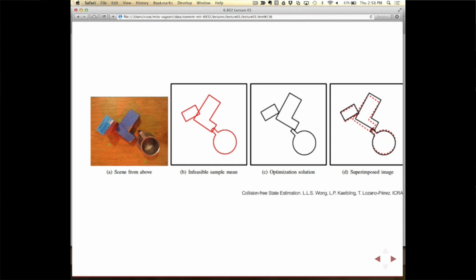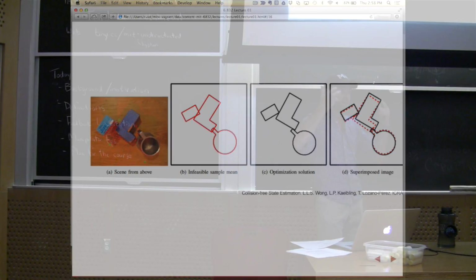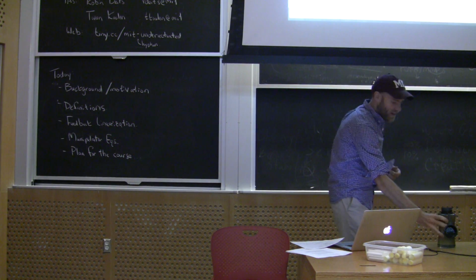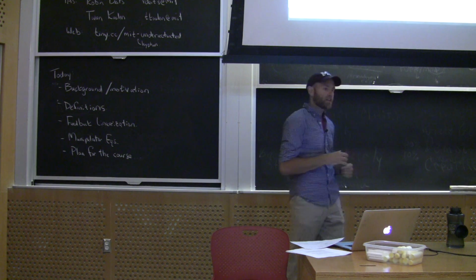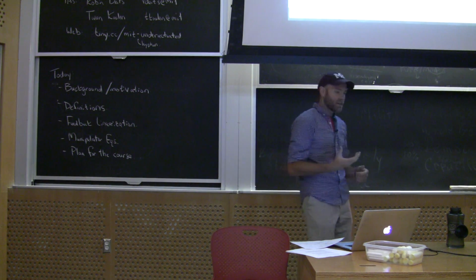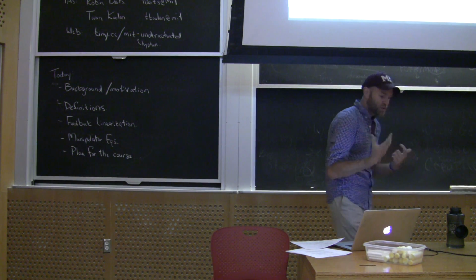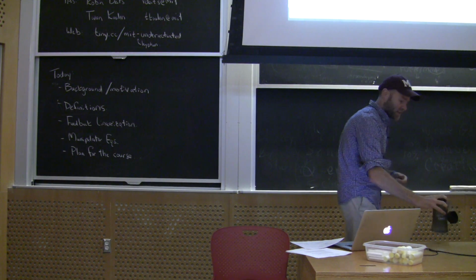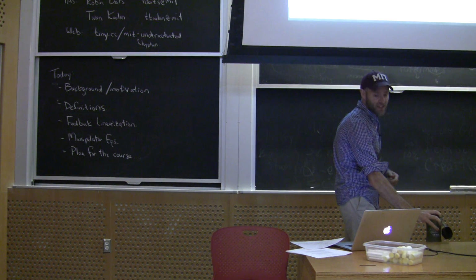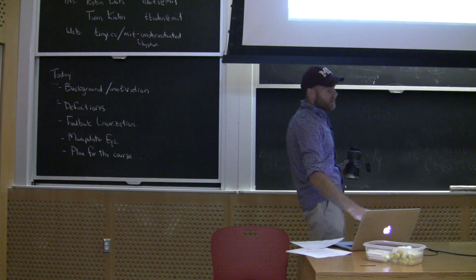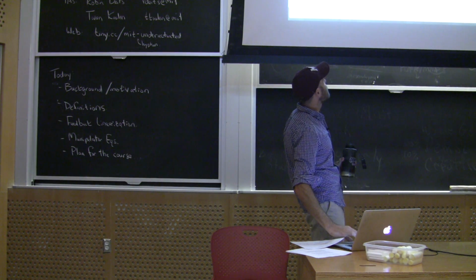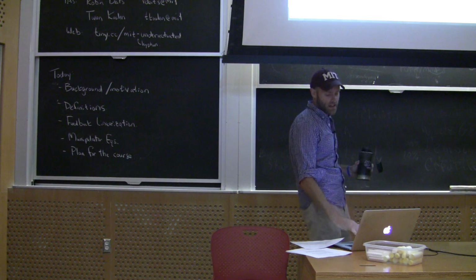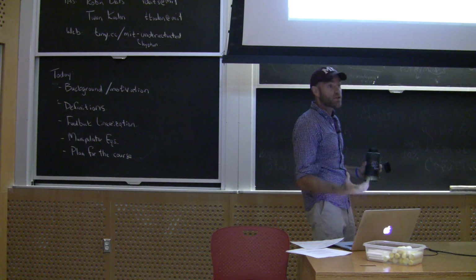One of the things he likes to talk about is the fact that most estimators that just use, let's say, a Kinect or a laser scanner in the head and look at point clouds off an object and try to estimate where the object is, have this annoying property that they'll give you some probability that the object is, let's say, in penetration with the table, right? It's stuck through the table, or multiple objects. Most of the estimators we come up with right now have things that are in collision, right? And his work here was trying to take them out of collision, okay?